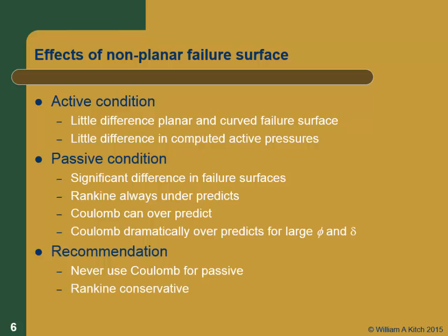Rankine is always conservative, so you can use it. And if you want the right answer, you should use a log spiral. So that's kind of the bottom line for passive.